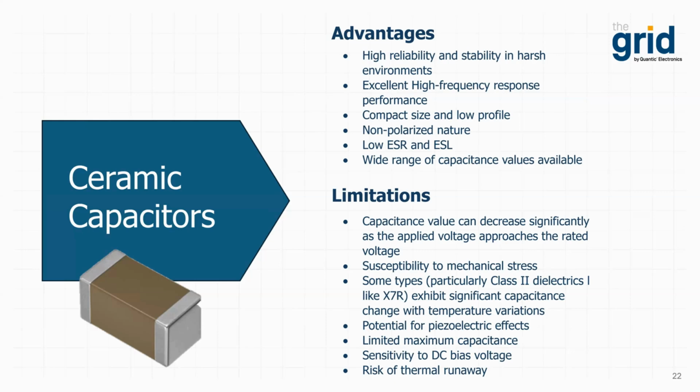Also, ceramics have the potential for negative impacts as a result of piezoelectric effects, which can introduce unwanted noise in some circuits. And they are limited in maximum capacitance values compared to other capacitor technologies, and typically they're available in up to 100 microfarads. They are also sensitive to DC bias voltage, which can reduce the effective capacitance in power supply applications. And finally, they do risk thermal runaway in high voltage applications if they are not properly derated.